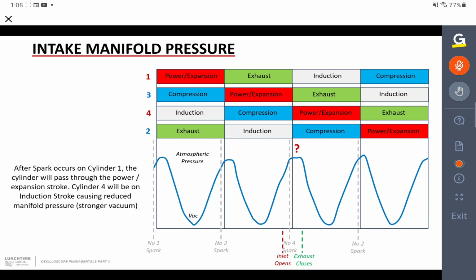And I've seen this a few times, and this is often an indicator that you've got a worn cam lobe or a worn cam follower. Something's not quite right with that camshaft lobe, and whether it's on the inlet or exhaust, you'd have to examine. But that slightly flattish trend, when all the others are fairly rounded, that slightly flattish trend with the sort of almost corners on it can be an indicator of worn cam lobe or worn cam follower.